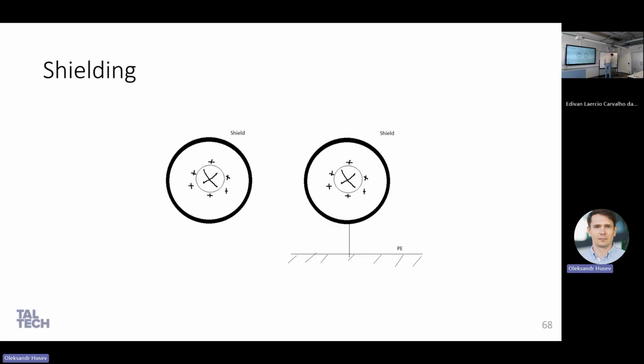And you have your 4-layer PCB, and your inductor is located somewhere here, schematically of course, and it creates propagation of electromagnetic field around. But if you use your protection earth, it's not necessarily connected. If it's connected, it will work in a different way. But you can create a Faraday cage to protect your digital and analog circuits inside the PCB.